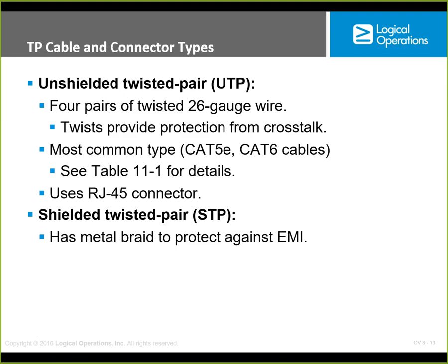What crosstalk is, if we have, I'm an electrical engineer, so I can hopefully do this. If we have a noise signal that comes in here on one of these wires, it's going to be induced into the other wire. When we twist the wires, we physically shift them a little bit so that when we get this one and we get these together like this, they're going to cancel each other. So we get some noise cancellation by using the twists.